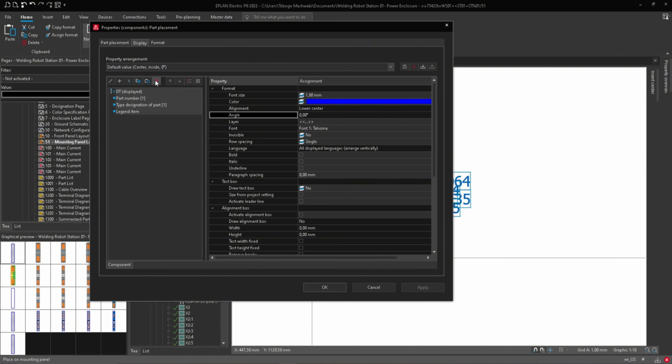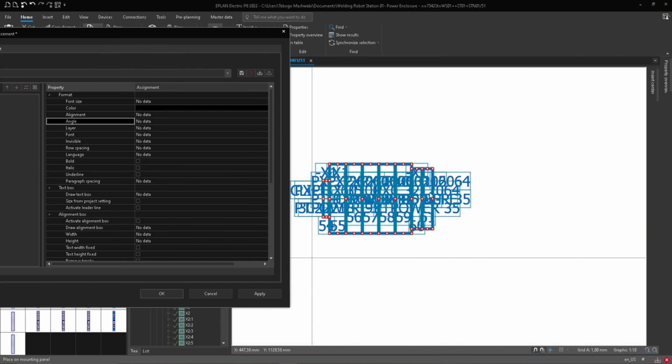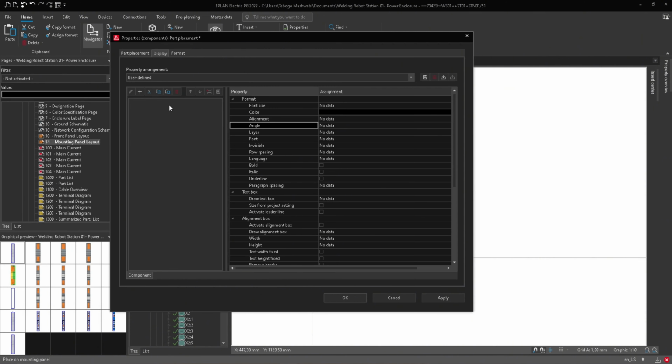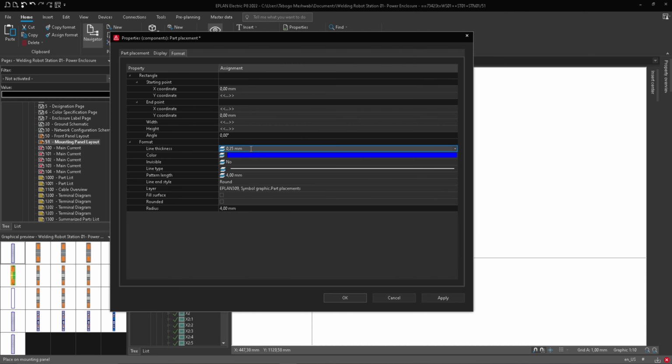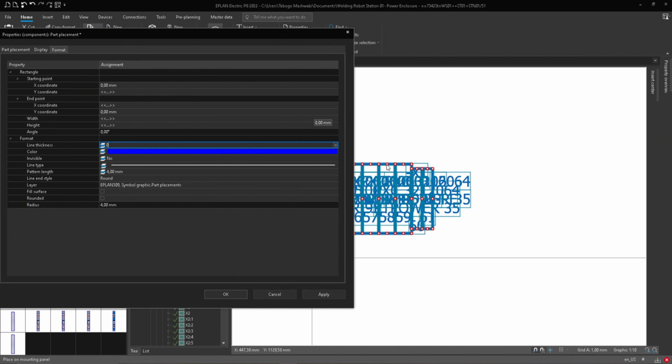So I'm going to delete this information. Deleting this information is just deleting all these numbers or letters or words that are appearing right there. And what I'm going to do, I'm just going to place this, and this is just to label the name and the visible one. After that, I'm going to change the line thickness. Basically, the line thickness is this line that's holding it. So this thick line, which is the blue one, I'm just going to place it at 0. So it will be at 0 millimeters, and I'm going to say okay to that.